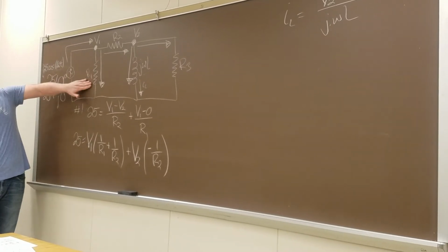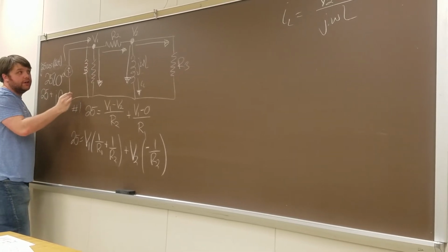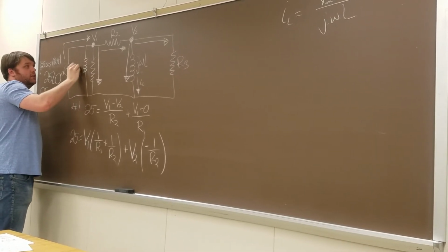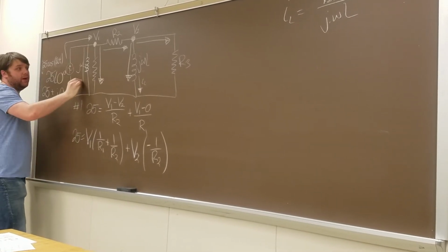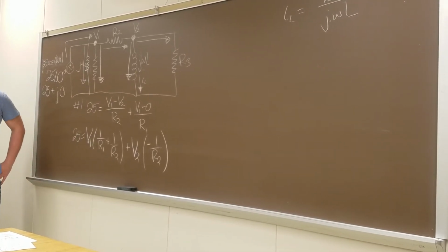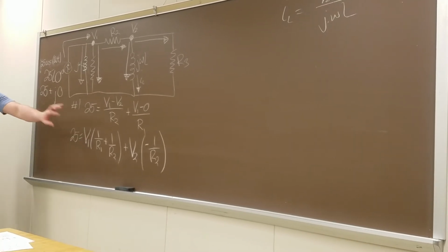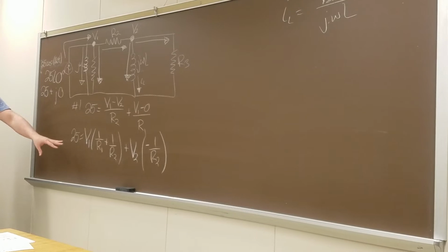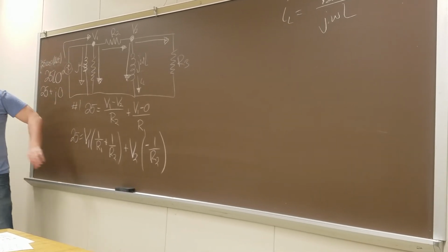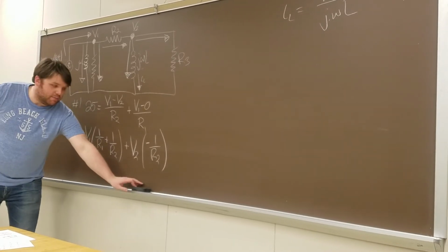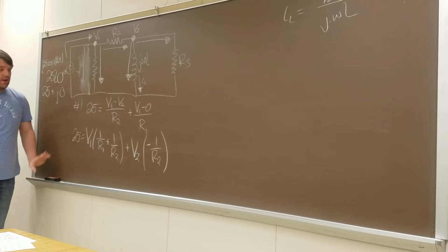So if I just wanted to add in another inductor here, so this was like j omega L2, well, now I have another pathway out. Okay? All this would do is it would add another plus 1 over j omega L. You do not have to combine these when you're doing KCL. Right? This is why MATLAB is your friend. So it allows us to simplify things. So I have this form.